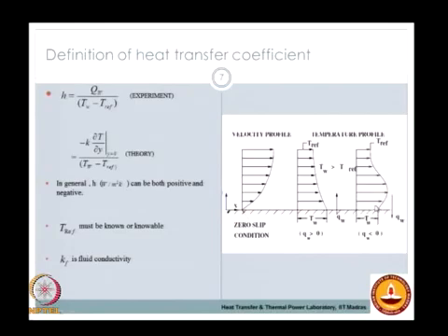Whereas on the right hand side, you have a flow situation where the wall temperature T wall is greater than your T reference, but you can have a jet of hot fluid, which is greater than T wall as well as greater than your T infinity, blown over the surface, and due to this you can have a temperature profile distorted in this manner.